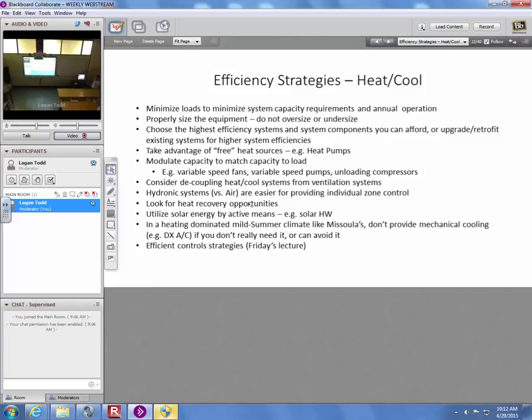But with residential hydronic systems, we do see where you've got one loop that goes to the radiator in that room, and a different loop that goes to the radiator in that room, and each loop has its own valve or pump. It's so much easier to do that zone level control, to say, I want heat in that zone, but I don't need it in that zone. And zoning obviously is good, because let's say you've got a guest room that you don't really need to maintain at 70 degrees when there's nobody in there, right?